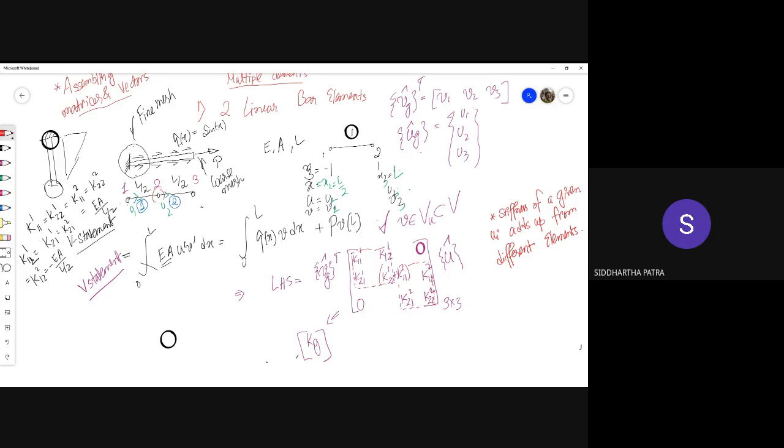For example, if there were more than 1 degree of freedom per node, okay, not only would there be addition in the diagonal terms, but also there would be addition in the off diagonal terms. So when you would be doing Euler-Bernoulli beam element or any form of beam element, there would be off diagonal terms as well, where you see this sort of addition.